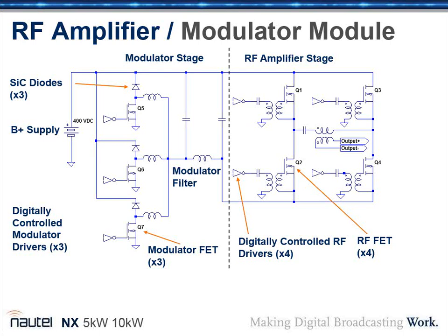Okay. And what is the typical frequency of each of these, or the total effective frequency? Is that where the 1.2 megahertz, whatever it was, comes from? 1.8 megahertz. Yeah, it's basically the sampling rate of the PDM. Because the transmitter has 6 PDM phases, they switch at 155 kilohertz each. Each edge of the PDM essentially samples the incoming audio signal. That's our overall effective sampling rate.